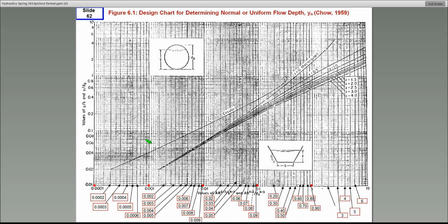Is the Hardy Cross method for the afternoon session only? Usually yes, but they might give you a simple loop problem with a simplified setup. All you have to recognize in the morning session is that the sum of head losses around a loop is equal to 0. So they could give you that configuration as a part of a hydraulics question. I just answered that in a very elementary way, probably.